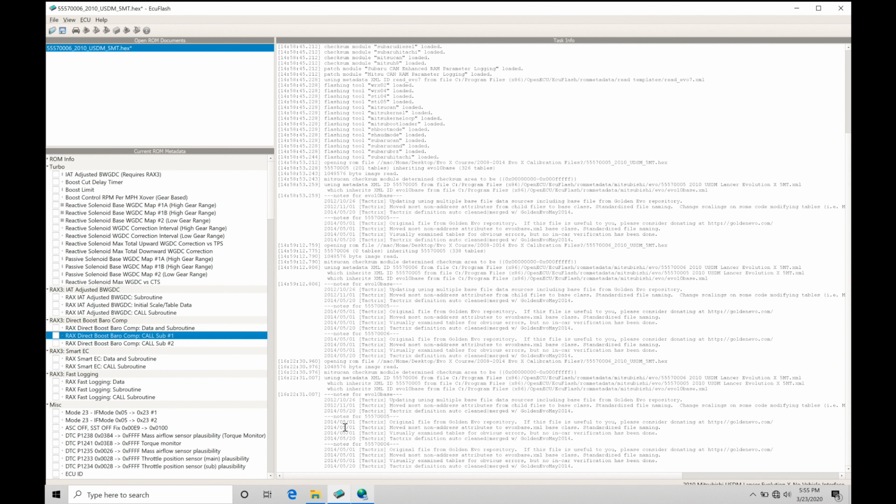So we're going to be looking here both in our ECU Flash software. We're also going to be taking a look just briefly into our EvoScan software of things we want to log. Then we're going to be taking a look at Megalog viewer so we can look at some example data logs I'm going to be providing here, so that we can build out our histogram to evaluate our spark timing and knock, and then also going in and taking a look at some specific things to tell if we have real knock or false knock, which can be a problem if you have a built engine or bigger cams. It's going to be throwing off the knock sensor calibration. So there's a lot of things to talk about here.